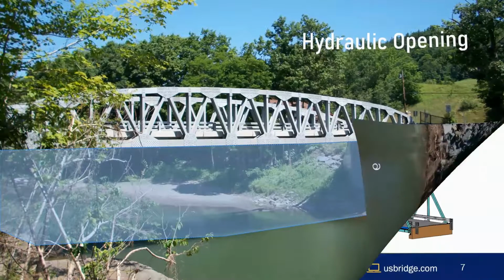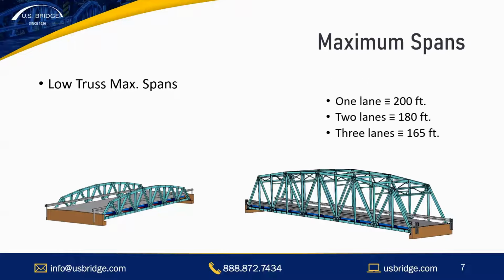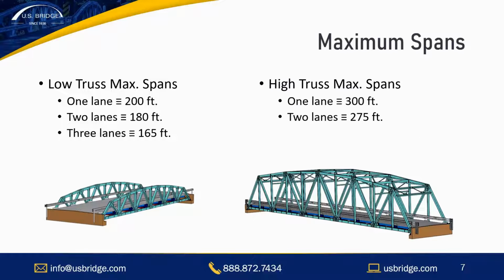So naturally, when we start to discuss these things, people want to know what are our max spans. What do we recommend for our max spans? We've got a pony truss on the left and a through truss on the right. So we like to recommend these lane and span limits. These are good rules of thumb for us to be able to design and fabricate.